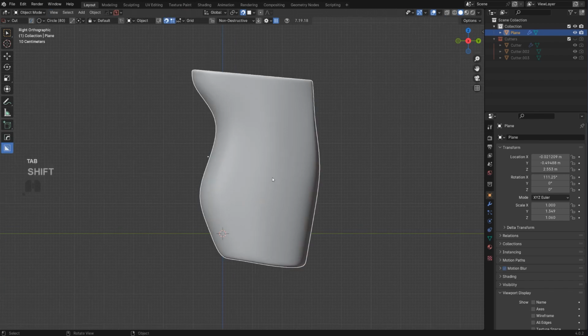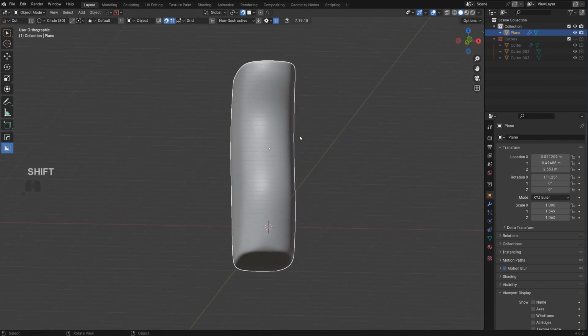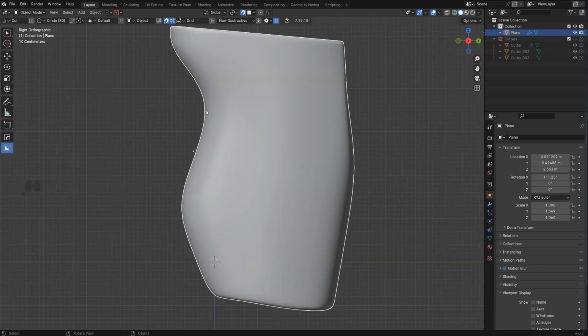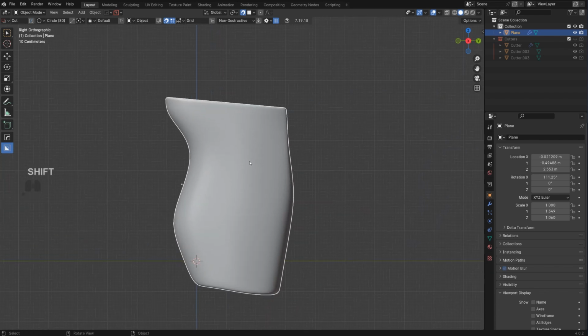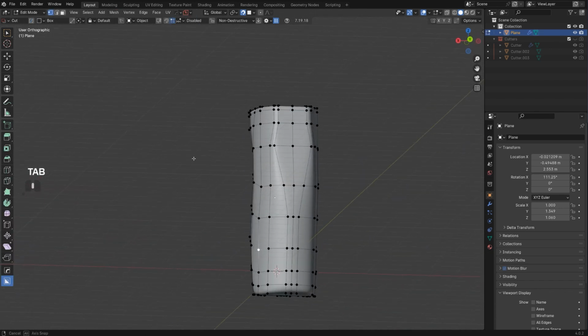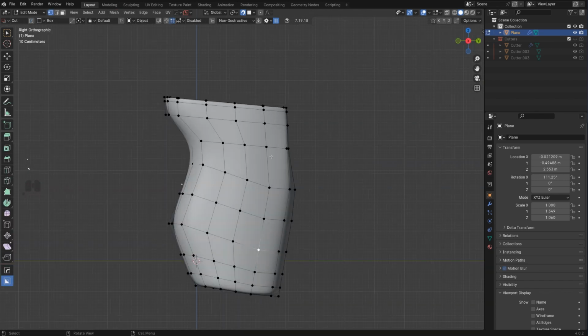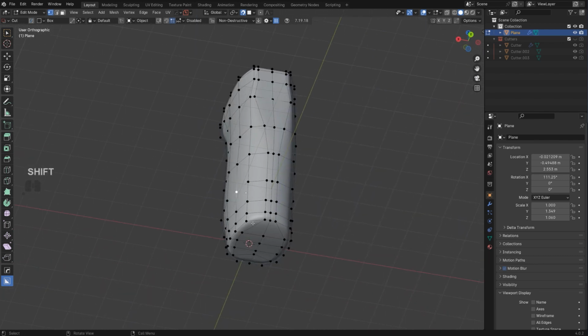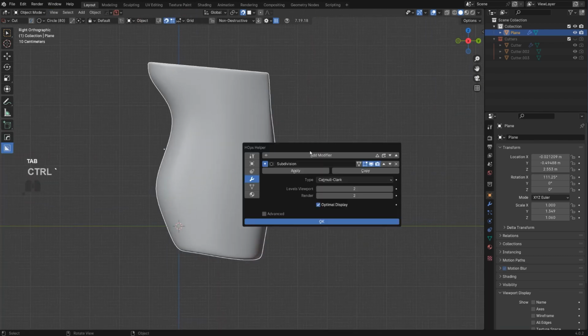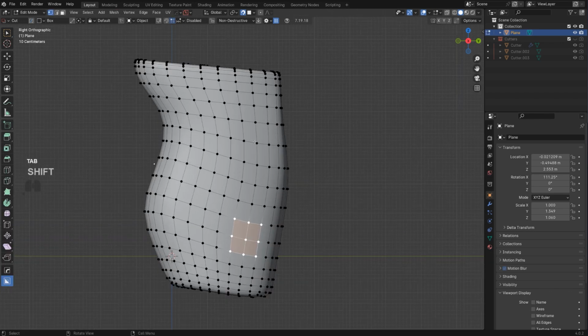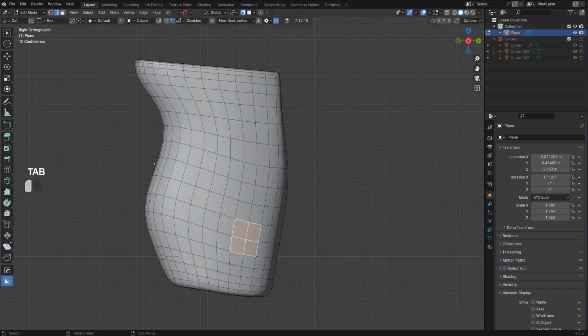So when you are certain that your shape is what you want, like this is the basic shape I want, and I'm happy with that, and I'm ready to add details like say paneling, screws, etc. You cannot do this on this level because the topology is too big, and you have a curved mesh, and you'll be running into shading problems. So what you need to do is apply at least one level of subdivision, right? And see if you have enough topo to start creating some details.